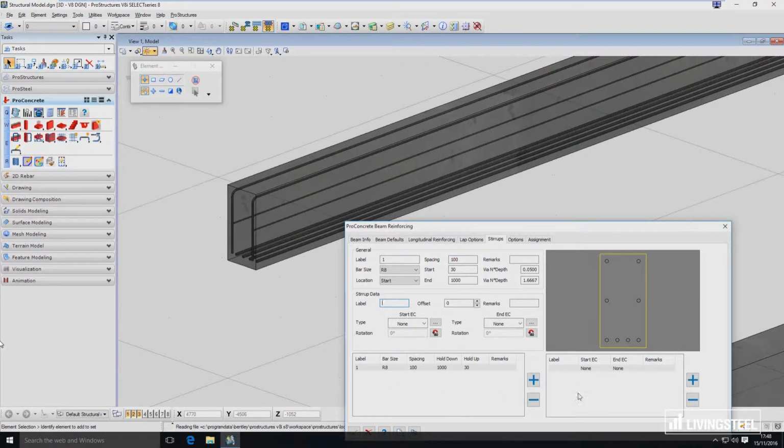So first I created a zone, now I am creating the geometry of that stirrup. It's going to have a label S1, and here I'm just clicking through on which bars I want to bend my stirrup. So I'm going to start here, go there, and you can see it's being placed, go down, go right, and go up. Here, as with all the bars, you can set up end conditions, so I will create a 90-degree hook on both ends, and that's just the first zone.